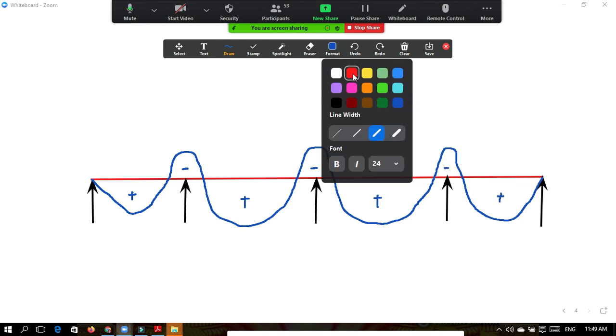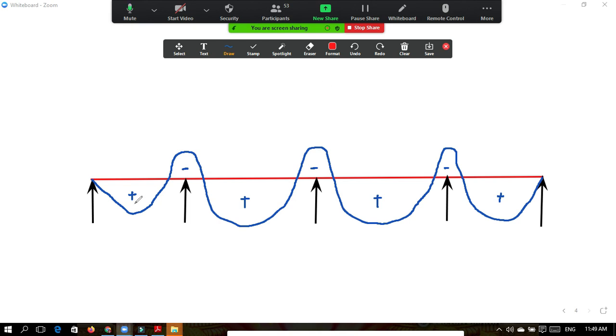Now again I will repeat the points of the bending moment, so that in the next lecture we will directly get the coefficient. Whatever may be the bending moment at this point, this is your point number 1. The same will be the bending moment at this point. This also I will call point number 1. Then whatever bending moment occurs at this point, at the support next to the end support, this is your end support, and this is the support which is next to the end support.